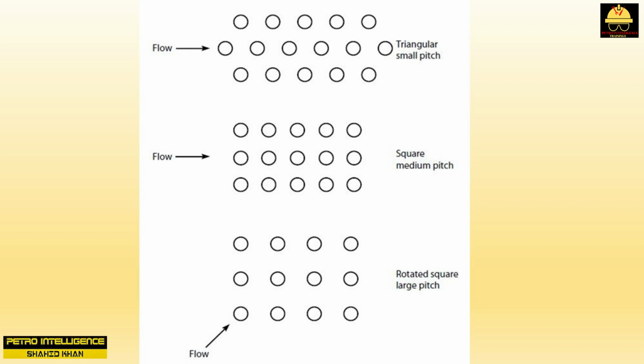Once the space between adjacent tubes is bridged over with deposits, the flow of fluid between these tubes drops to zero. The local heat transfer rate drops close to zero. Overall, shell side ΔP rises as flow is diverted away from the restricted zone. Using the larger tube pitch will reduce the number of tubes in a shell by about 35%. But in a fouling service, this may greatly increase run times between cleaning and, in my experience, is a worthwhile incremental investment.